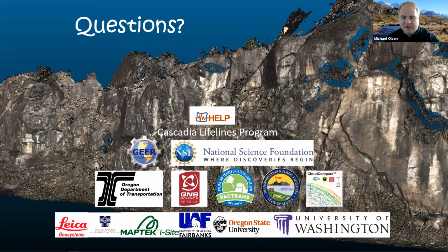We generally avoid interpolating very large areas, because you can get a lot of false positives that way. Also, when we do that clustering approach, we keep track of whether the baseline surface or, sorry, the new surface had holes filled, and we can weight those differently. So if something is based on more interpolation, we don't use those in the actual development of the magnitude frequency curves, whereas we do use something where we've got pure scan data.